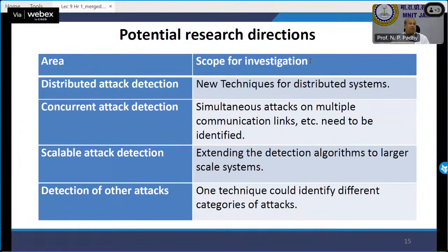So those substations are good, but prone to cyber attacks. Example, when you talk about PMUs, they are prone to cyber attacks because the data is coming to Earth actually through space. I can create a disturbance and give wrong data. So what I'm expecting as 10 gigawatt, it will tell me 100 gigawatt of load. So then I'll start my generation and then it will vanish. It will go back to the 10 gigawatt load. So what will happen? There is a huge mismatch. I ramped all my generators thinking that a load increase is happening, which is not true. It's gone. Very exciting.